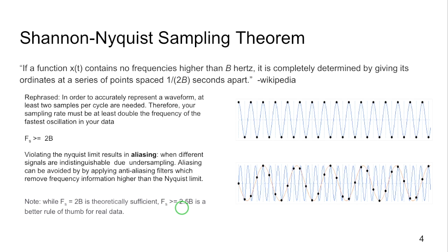The real signals are not as stationary as the ones I've drawn here, which is to say that the statistics of the signal drift at least a little bit over time. In addition, we are typically interested not just in the frequency information, but in the amplitude information. And if our samples don't fall exactly on the peaks and the troughs, then we're going to be underestimating our amplitudes unless we have sufficient sampling.